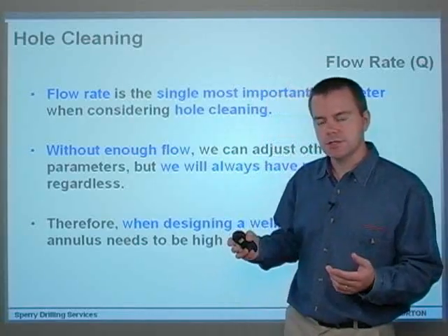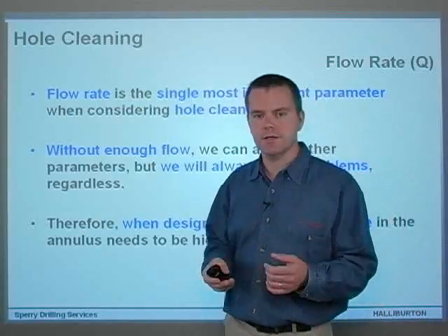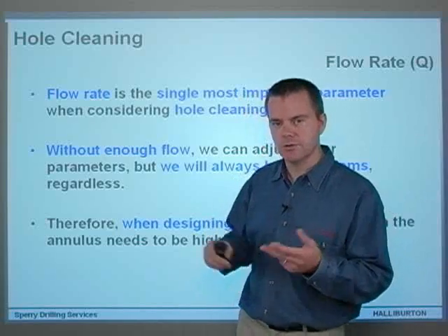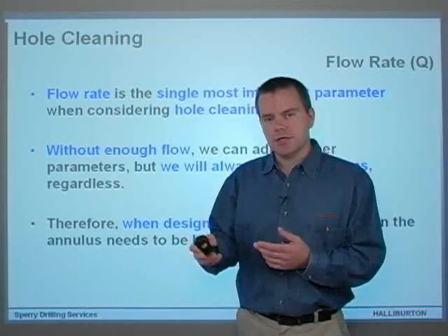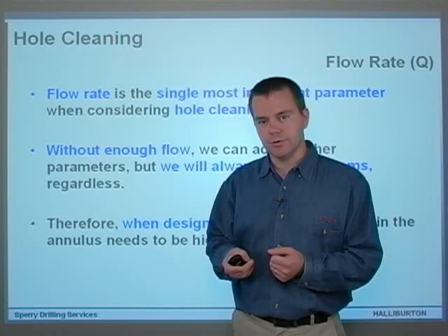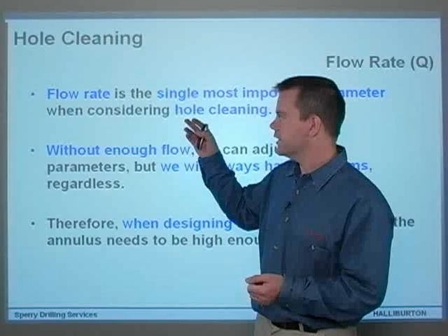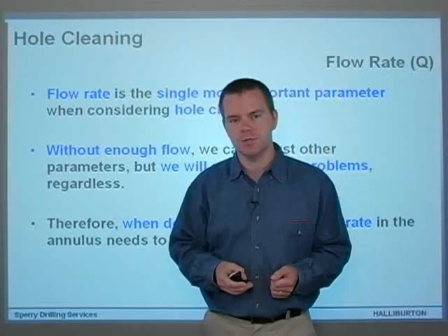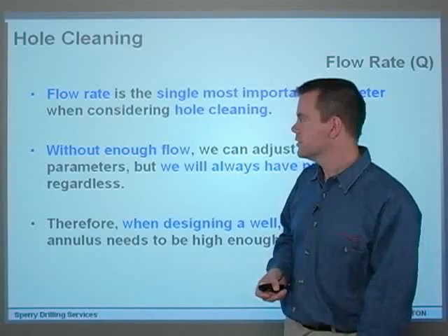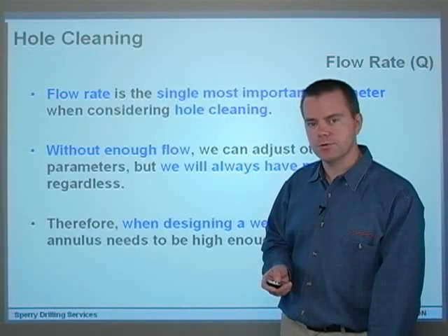And when they look at it, a lot of the time the wellbore has been planned with things like sweeps and rotation and wiper trips and all sorts of secondary means of dealing with hole cleaning problems. But when some of these guys actually have looked at the data, they found that the flow rate that was being used was actually just not enough to clean the hole in the first place. So it's the single most important parameter when considering hole cleaning.